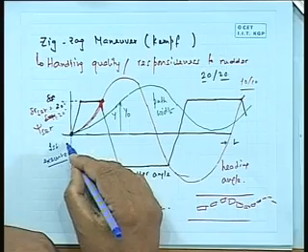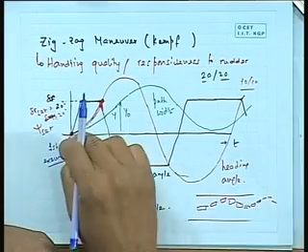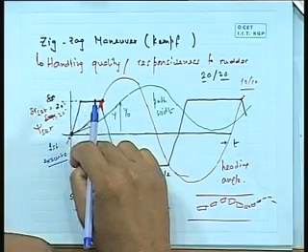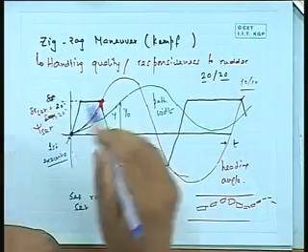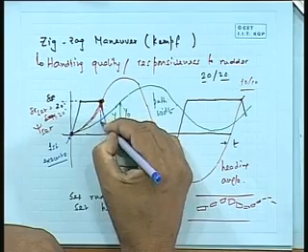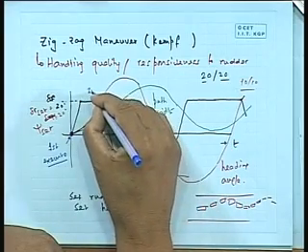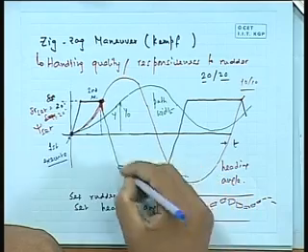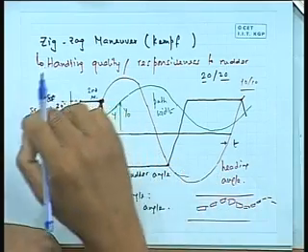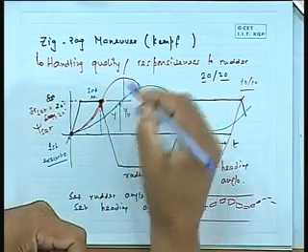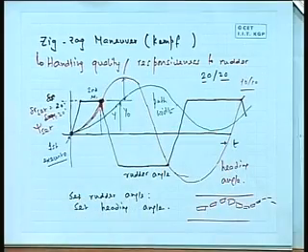At this time, this is T here. This is the point of time where you have made the first execute of rudder. You have given the rudder angle to plus 20 degree. This time is the time for second execute. Similarly here, third execute, etc. The 1, 2, 3 executes are the times when you have changed the rudder angle. An important thing that you find out is what is called overshoot yaw angle.